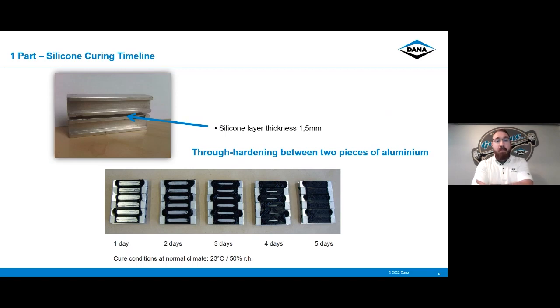You're going to see something like this. The outside formed a skin layer. You're going to see that curing process starting, but the inside is not cured yet. And so you're going to scrape it all off. You're going to have to clean that surface back down to the metal so that you can get good surface to surface adhesion and apply the silicone again.